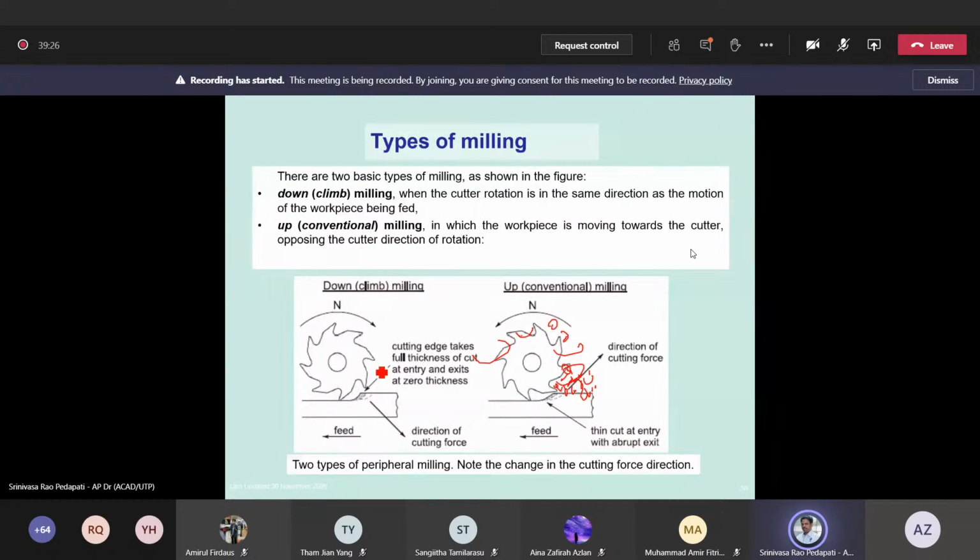Whereas here, it hits and then goes back. So ahead of the tool in down milling, it is clear, there are no chips. That means in down milling, the tool always hits a new surface. There are no chips ahead because the chips are thrown away to this side, onto the already machined part. So no problem. Whereas here, the chips are ahead of the milling cutter, on the surface that is to be machined. That causes some disturbance and problems with surface finish.